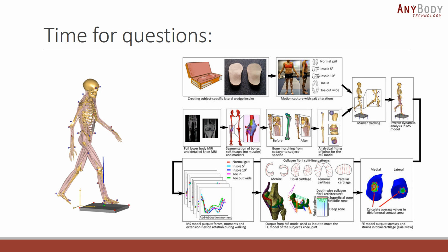Yeah, it does. So it's a good point that if you want to capture the full anatomy and the full details that we have in the finite element model, we would have to include it directly into the multi-body dynamics. The issue with that is that it will be very computationally slow. So the link to actually do this is the force-dependent kinematics model that we did. We assumed in that model that the bones are rigid, but the cartilage is deformable.